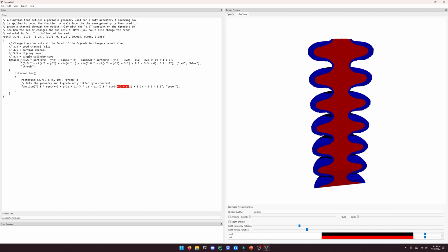It's a function of x and y, which means it'll extend kind of forever in the vertical or the z direction. And as such, like I talked about in my mug example, the constructive solid geometry example video, I bound that, or take the intersection with a bounding box to make sure that doesn't extend forever. We actually do define a stopping point.